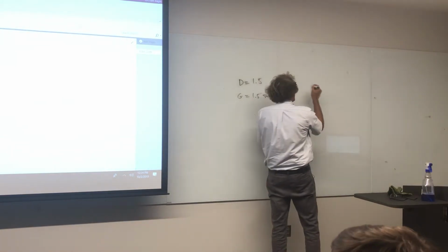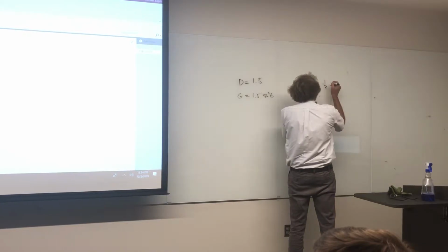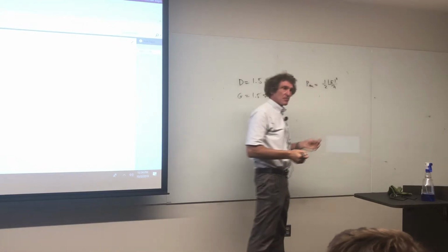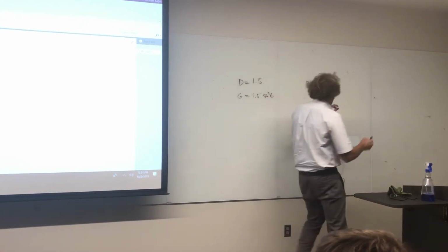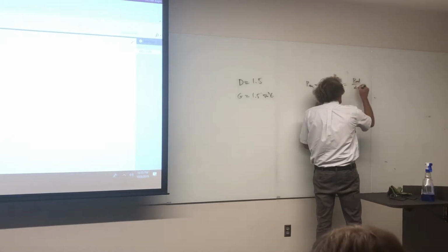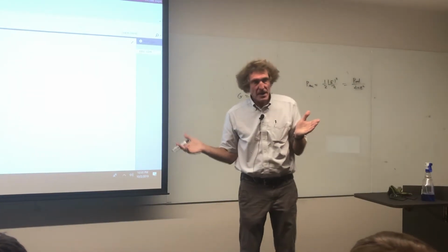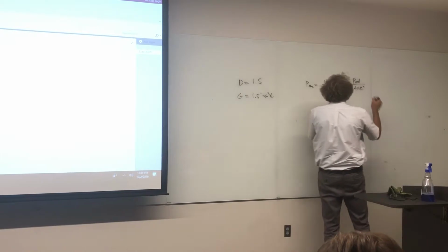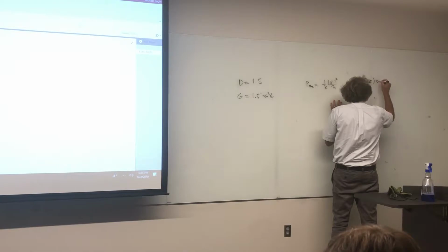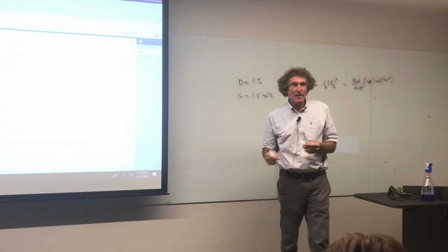So if you wanted the average power density, you knew that was 1/2 the magnitude of E squared over eta at that range. What does that actually equal? It's equal to the total power radiated over 4 pi r squared, if it's an isotropic radiator, correct, class? Then your gain would go here, and it would be equal to 1.5 times the sine squared of 45 degrees. You could get the power radiated that way too.